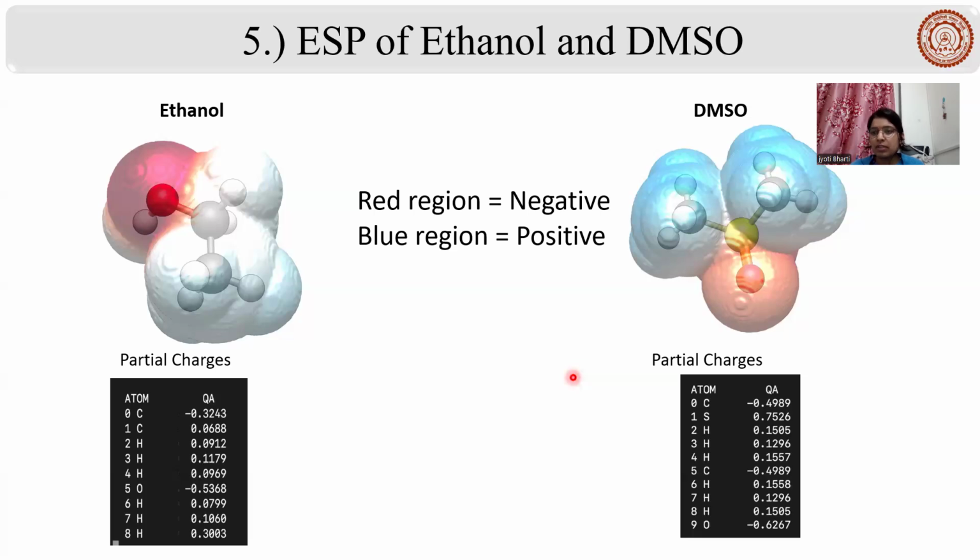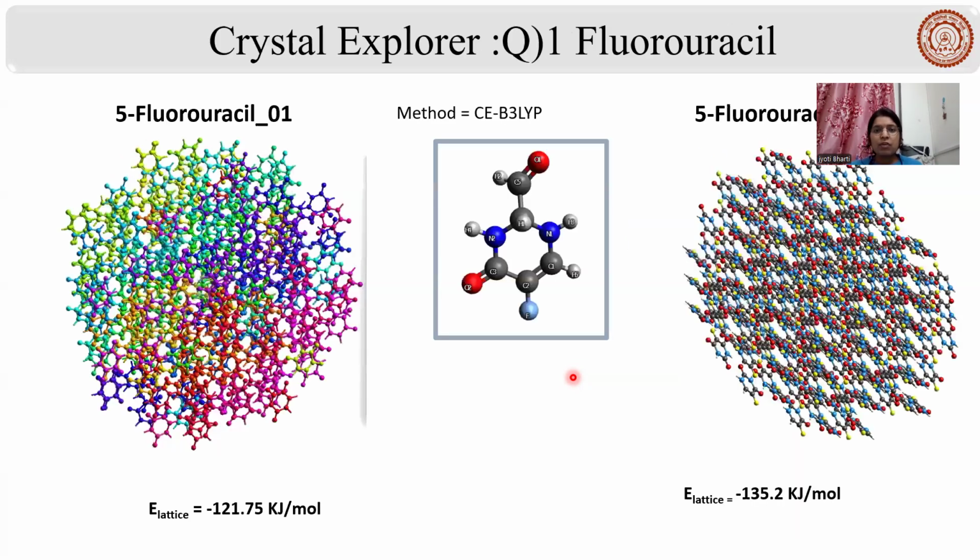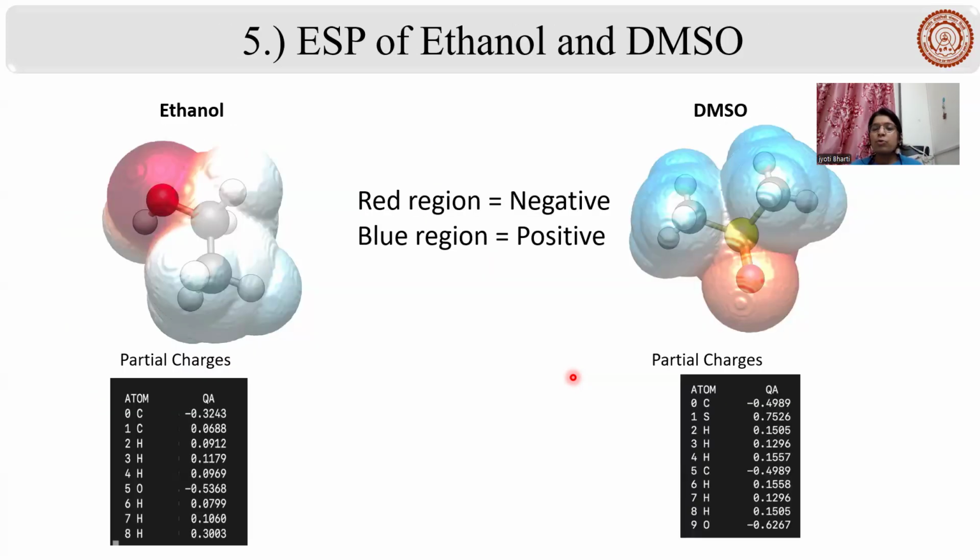So we just have to click on the particular dialog box. We can explore more things, like if we want to calculate IR spectra, or the ESP, and we can also create the van der Waals surface, and know the partial charges and the energies at each step while optimizing. So at each step, you can calculate what the energies were. So this was the part for our ORCA software. I hope you have understood how to use the ORCA software.